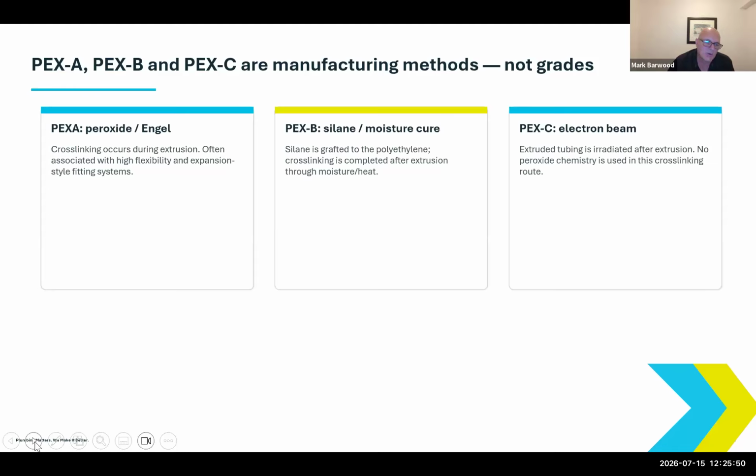So we try and get all the oxygen out of the system. If the pipe is able to let oxygen through, you wouldn't be able to use it in those systems. So heating pipe is always oxygen barrier. It's something different than the potable pipe that I'm mainly going to talk about. I don't have heating pipes, so I'm not going to spend a lot of time talking about it. But just to know that if it is a heating application, that's going to be oxygen barrier pipe.